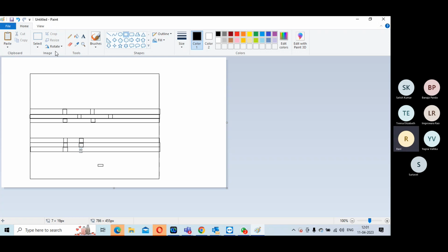You cannot have something like a 4x mux with that ECOable cell. So for the ECOable cell you will have to ask for a special map. They will tell you, if you have used, let's say, a big ECO cell, that cell may have different possible swaps to other standard cells, because you have to swap that first, and only then do your metal changes.